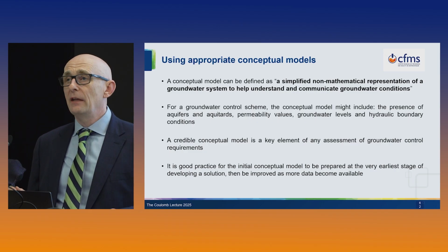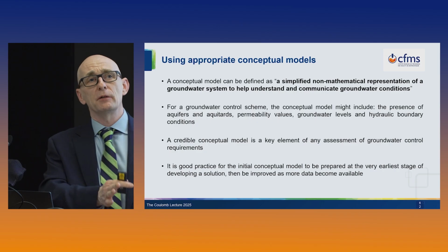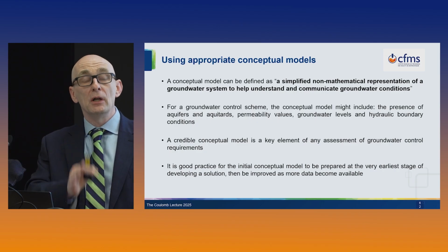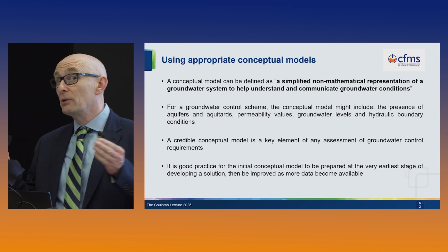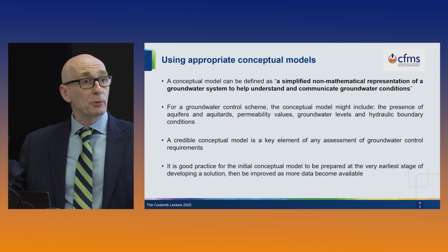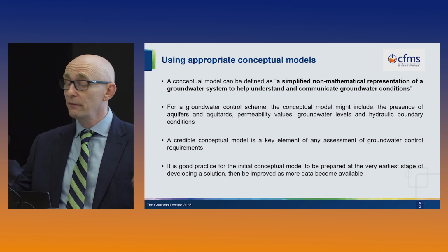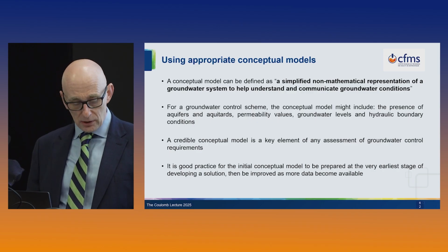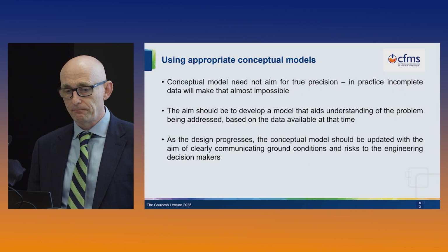I'm a great believer that you should have a conceptual model from the very start of a project. You shouldn't wait until you have a design. For example, I like to have a conceptual model to help direct the actual investigation, because if you think there might be multiple aquifers, then your investigation would need to try and confirm that. And obviously as more data becomes available, your conceptual model should evolve.